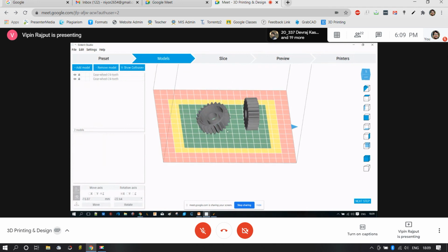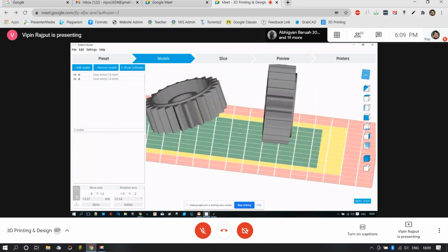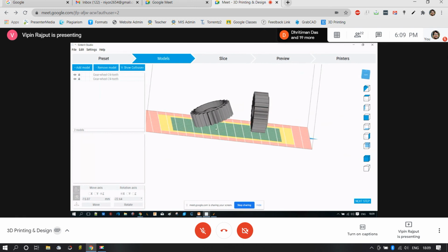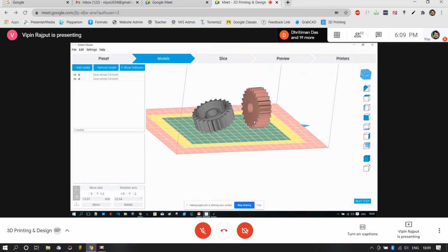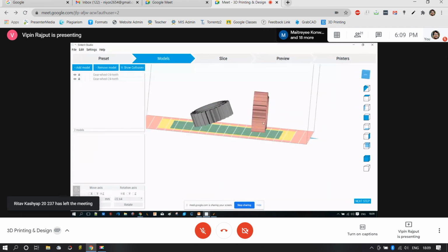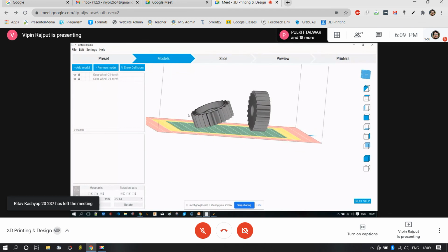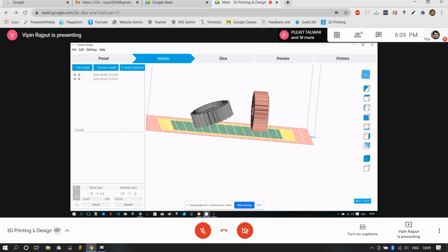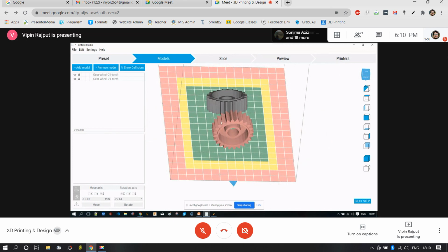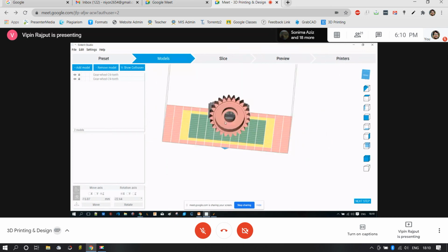And the reason is, even though it looks like it has a larger surface area for the laser to print, actually each layer will have less surface area to cover by the laser. Yes, exactly. That's the only reason why I asked this question, and I presume you have understood it well. Even in this case, the laser will experience a greater surface area to be exposed to, and the features which are supposed to be kept at an angle are actually kept perpendicular to the surface. Further, the formation could deteriorate the features.